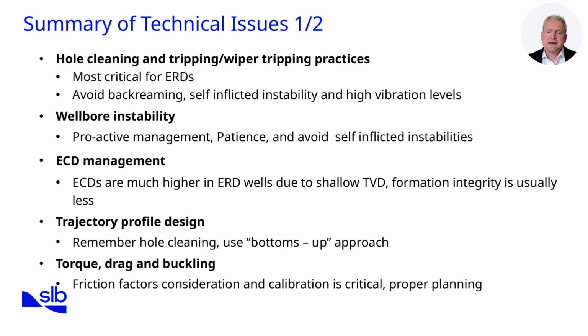Equivalent circulating density, or ECD, must also be managed closely. In ERD wells, ECD tends to be much higher because of shallow true vertical depth. Formation fracture gradients are lower, leaving us with smaller margins.